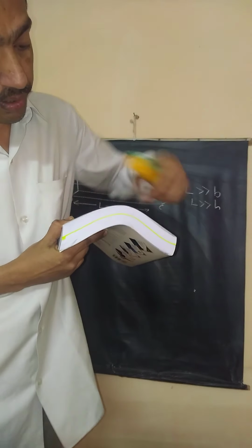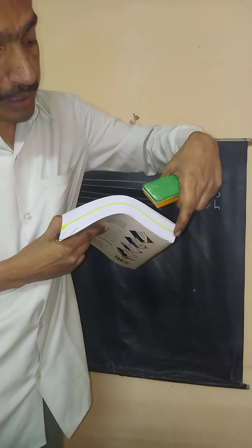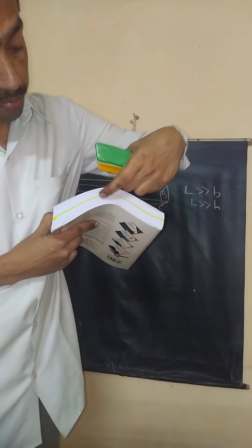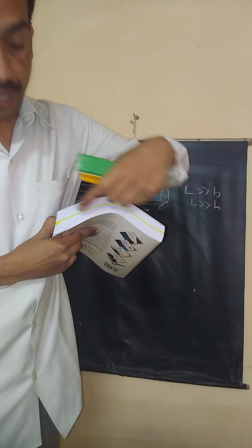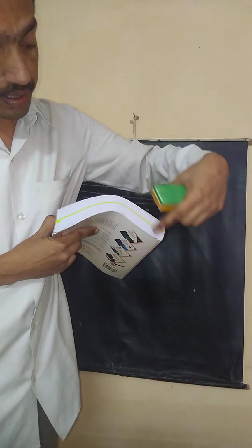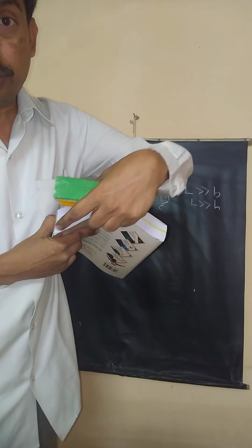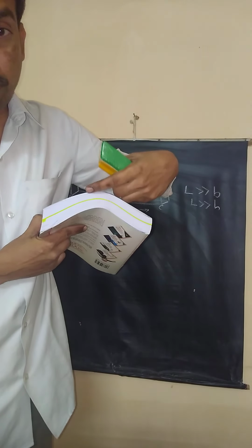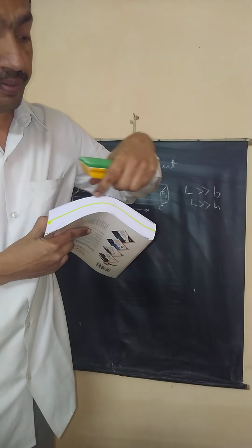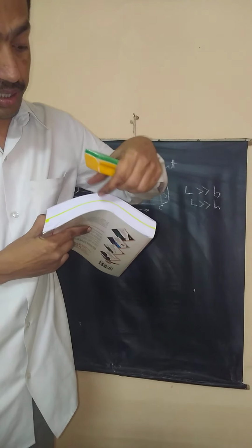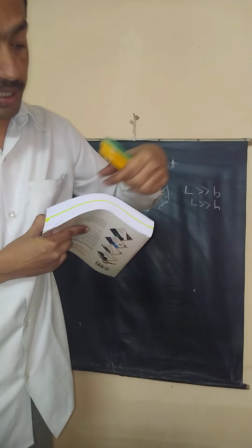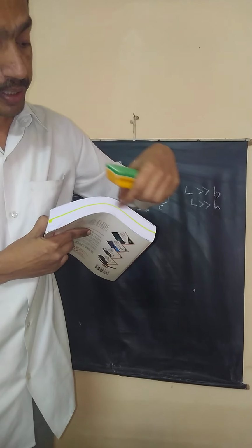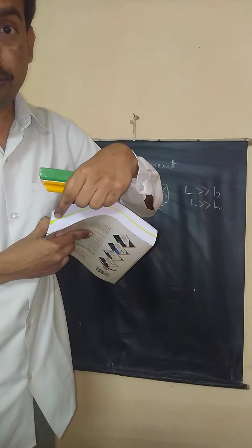Please observe, below this central portion, these layers below this central axis are expanding. Whereas layers above this, in this portion, you see contraction. Correct? Some layers are expanding, some layers are contracting. This layer which is not changing is said to be the neutral axis.